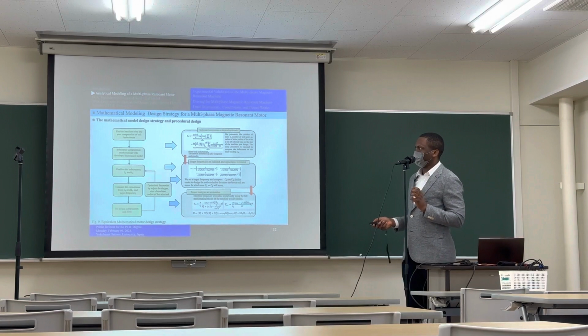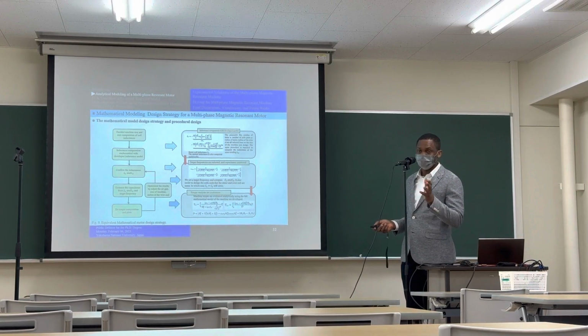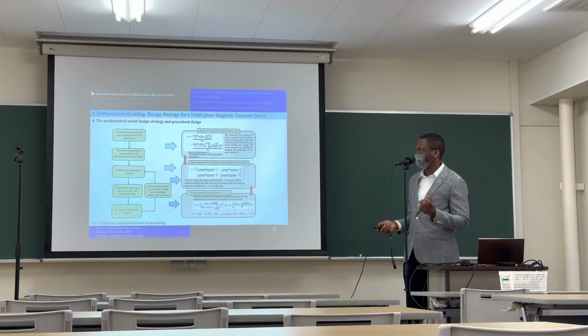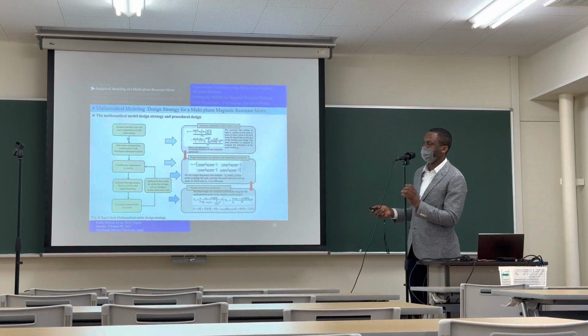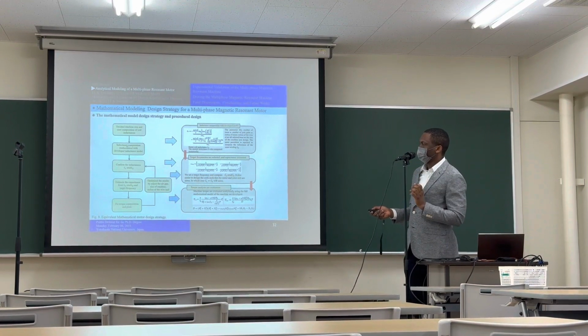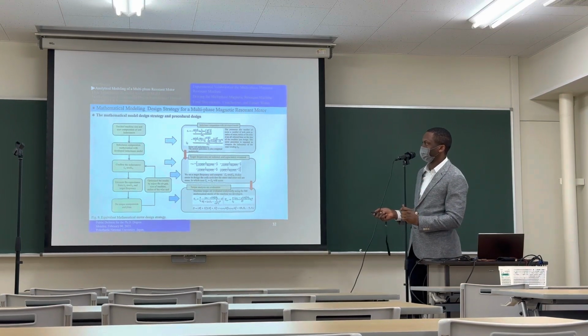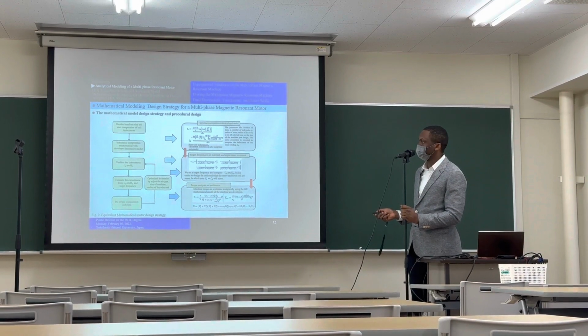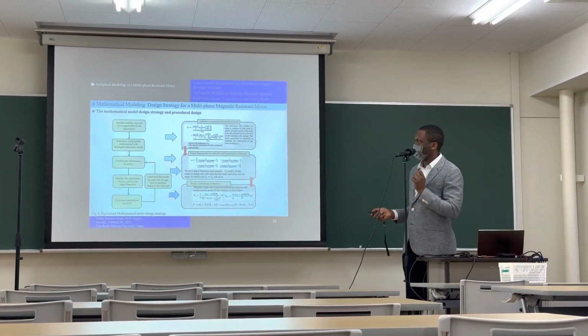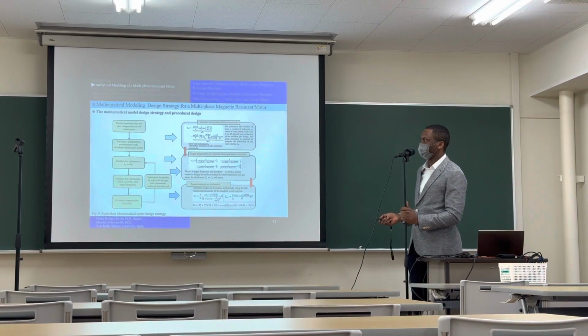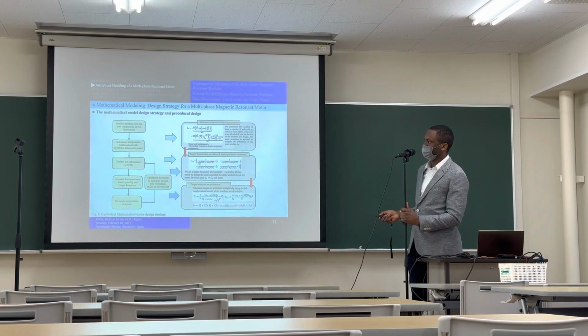Then we come out with a design methodology that you can follow if you want to use the analytical method that was developed. For the design methodology, the first thing is to decide the size of the machine. That is the outer radius, the inner radius, the coil and all that. From that size, you can calculate the inductance of the machine. Then you choose a target frequency. With the resonance frequency, you can estimate the capacitance that is needed. Now you have the resonance frequency, you have the inductance calculated, and then you have the capacitance value.